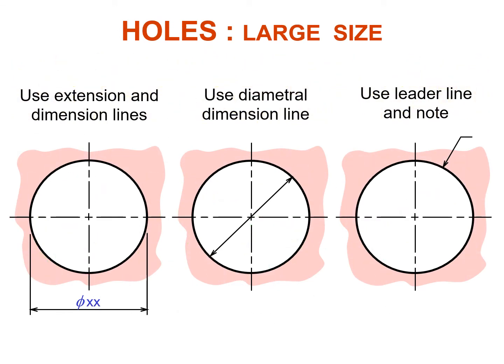Then for large holes, use extension and dimension lines. This is what we use. We can use extension and dimension lines also for large holes. We can use the diametral dimension lines, which is drawn inside the hole, and we can also use the leader line.